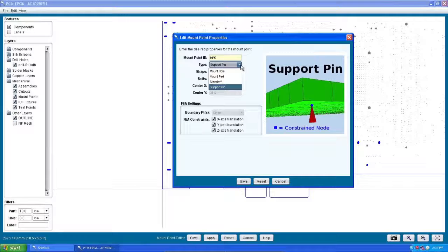Okay. Let's say I just use a simple standoff, like a nylon standoff, we see on a lot of these kinds of boards with a screw going through. Well, if it's screwed down, I would definitely use the mount pad. If it was one of these slotted or butterfly clip kind of things, then I would go to our standard standoff definition, which allows some rotation. The cheaper the attachment, we go from mount hole to mount pad to standoff to some extent. Yes, a good guideline to follow.